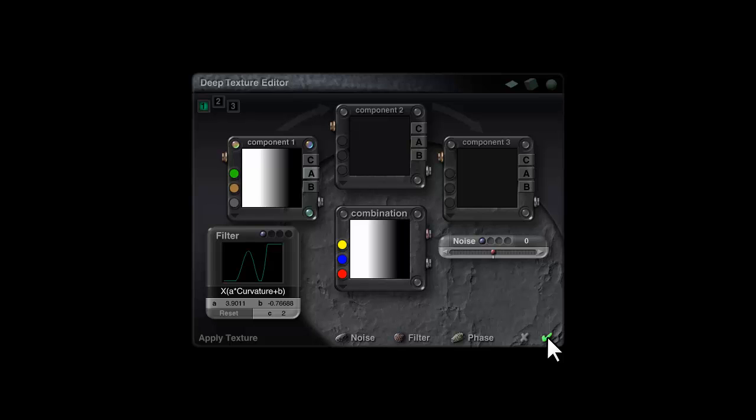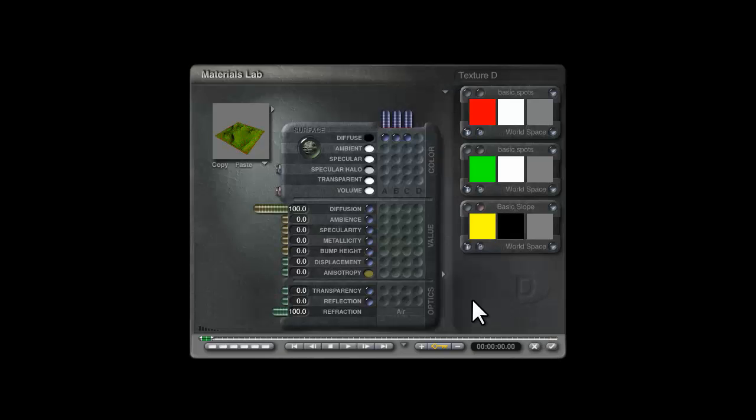And the advantage of using a picture is that we can process that picture in, say, PaintShop Pro and use smoothing on it, and that'll reduce the effect of these hard edges. So what I'm going to do now, because this is an alpha output, is switch ambient control over to this output and get rid of the diffuse response. So this will give me an ambient output based on the curvature.